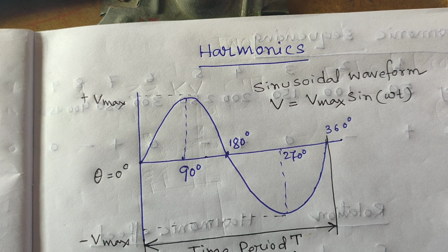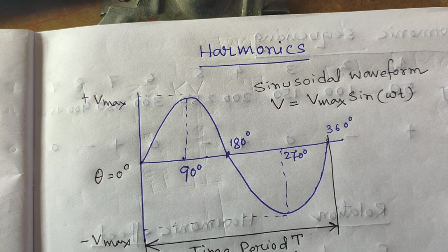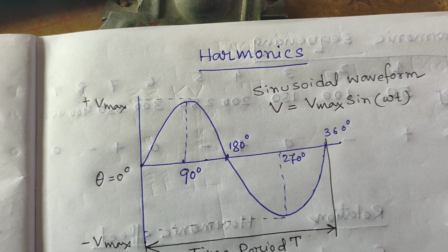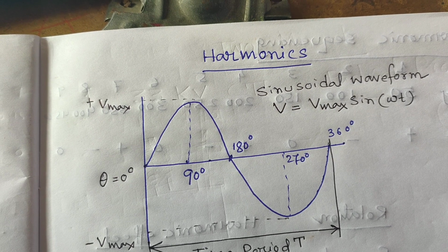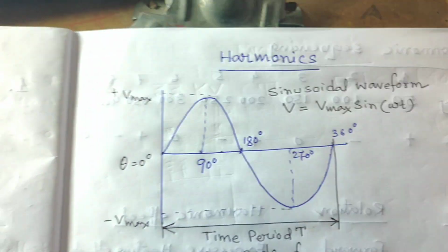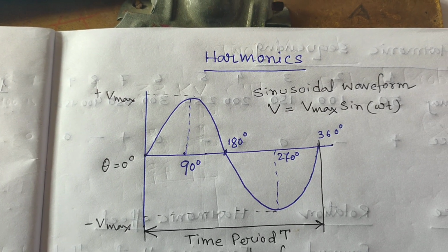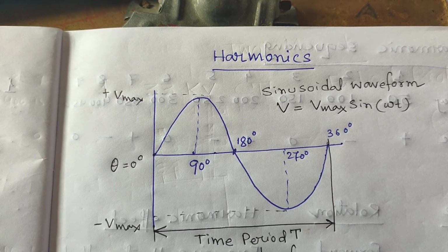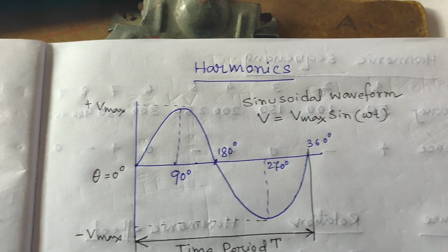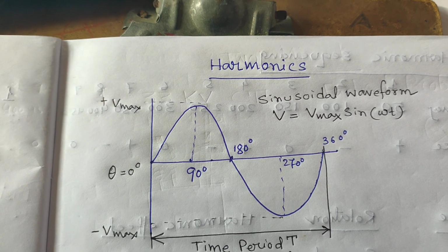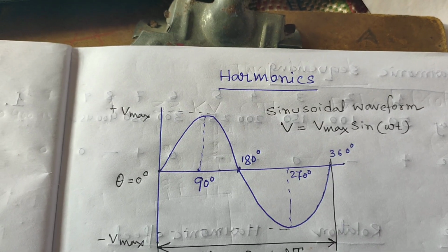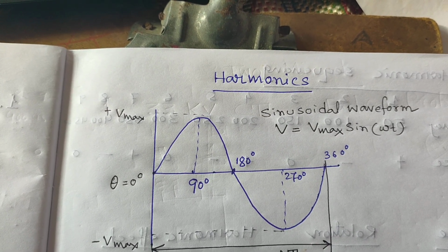This is due mainly to the fact that the current drawn by the load does not faithfully follow the sinusoidal supply waveform, as in the case of a rectifier or power semiconductor switching circuit. Harmonics in the electrical power distribution system combine with the fundamental frequency 50 Hz or 60 Hz supply to create distortion of the voltage and current waveform. This distortion creates a complex waveform made up of a number of harmonic frequencies which can have an adverse effect on electrical equipment and power lines.